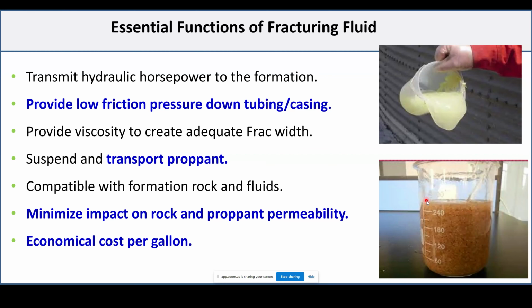So it's not only one test, it's a group of testing depending on the reservoir part that you have. Clay inhibitor will be CST or oven proppant embedment. Surfactant, column test, Ahmed cell. Scale inhibitor will be scale loop test. Biocides will be bacteria killing study. I think that is the majority of it related to the reservoir side.